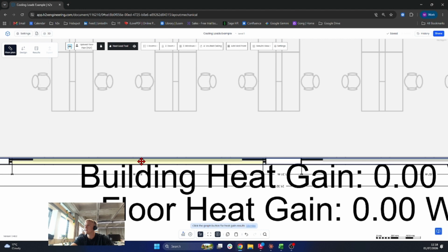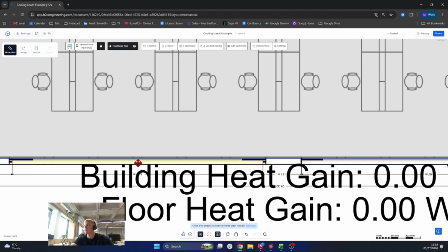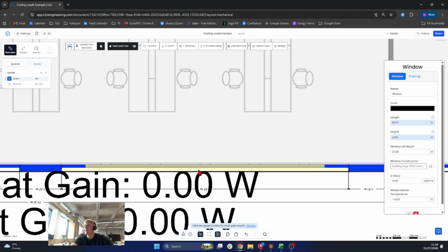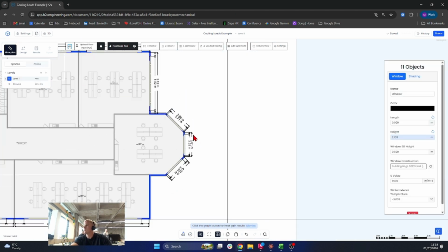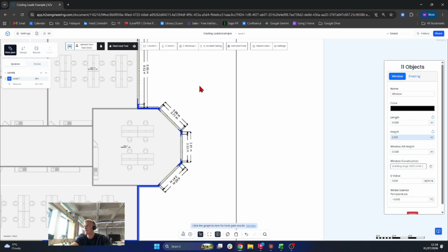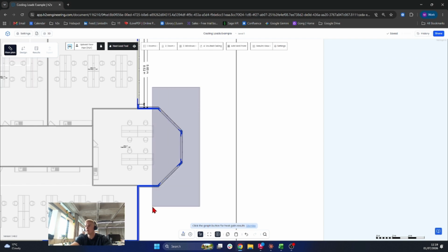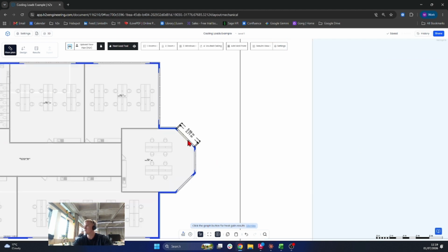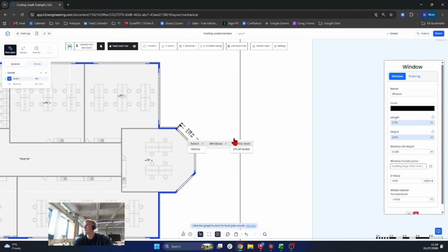And then we can slide it across just to line it up with where the window's shown on the plan. Now, if you want to do that on a bulk basis, just do a left click and then a right click, select Windows on this level, because I'm going to go over to these smaller windows, hold Shift, do a right click and drag from right to left, which will give me this box. Holding Shift will deselect those windows, meaning that I can adjust the rest of them to 8.5. And then I can do the same process, left click, right click, select windows on this level.